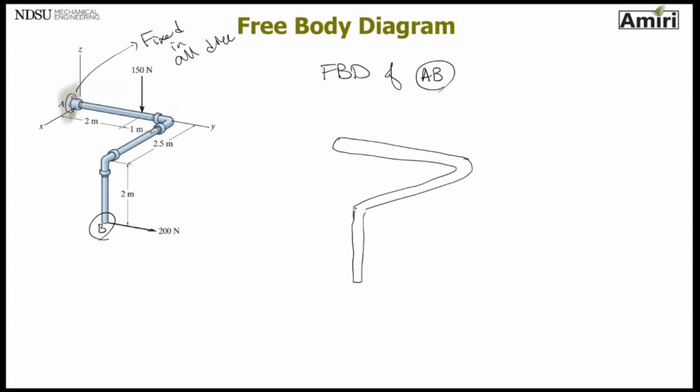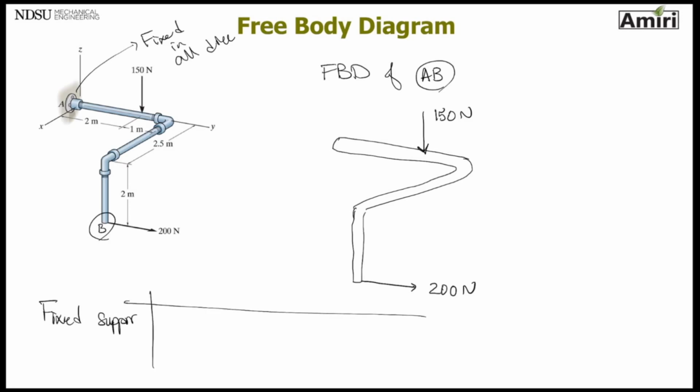Step 2, put active forces. I see one force of 150 newtons here. I see another force of 200 newtons there. I don't see anything else. Step 3, reactive forces. A fixed support. I'm going to do this a little bit quicker. X, Y, Z, MX, MY, MZ.